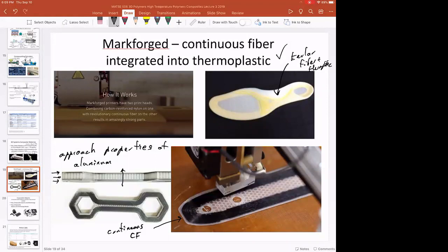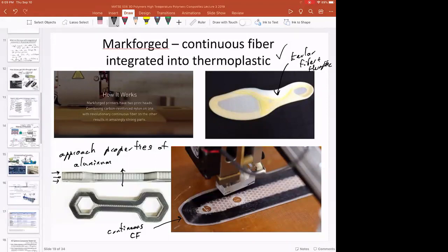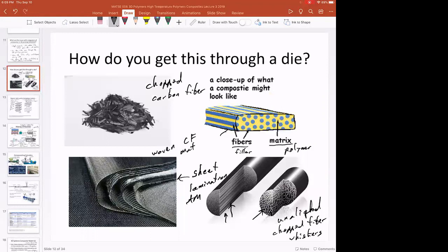Whereas if you have a woven composite, or if you've ever looked at a bike frame, a carbon bike frame that's not finished, you can see the composite fibers going in all different directions, and that's what gives it the strength. So the fibers are the high modulus part of this, and so they're very strong when you pull on the fiber in the long direction, but the matrix now provides the adhesion between fibers.